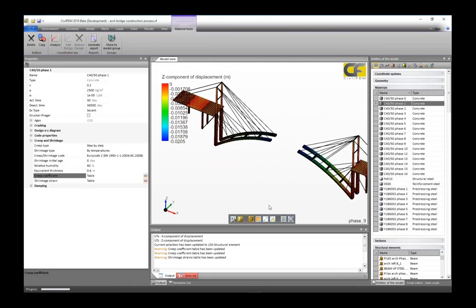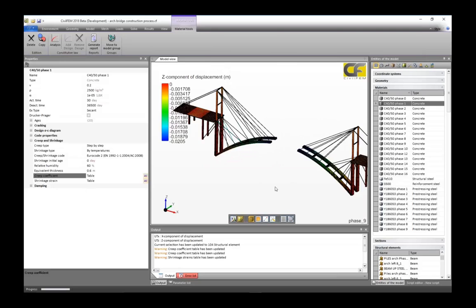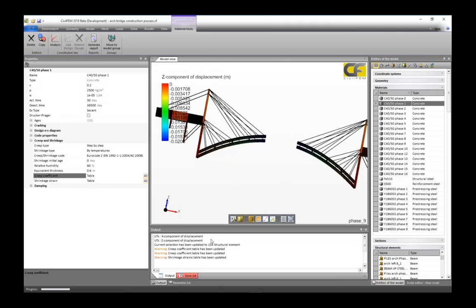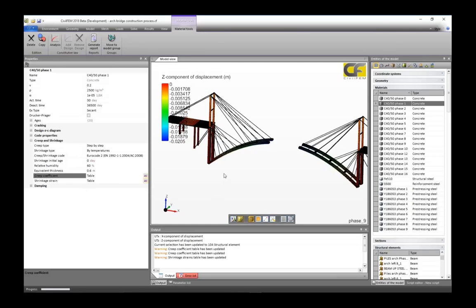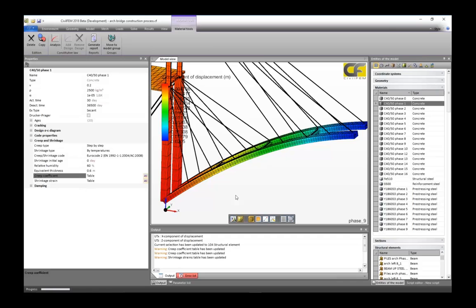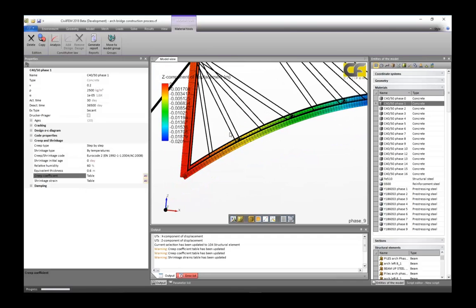So what we are going to do is calculate pre-stressing on every one of these cables to make the vertical displacement equal to 0. We can do it manually, solving and modifying and solving again until the vertical displacements on all these points, where the cables are anchored.